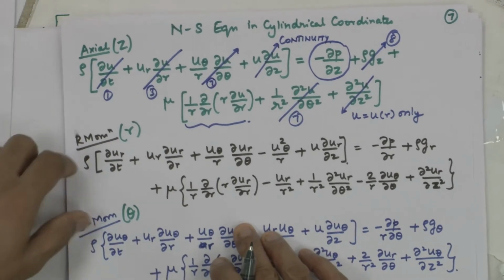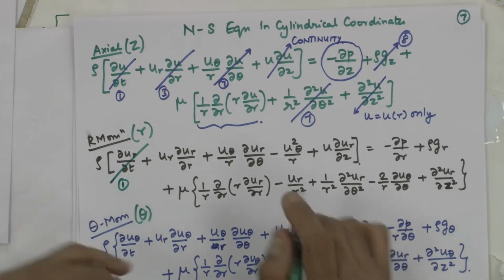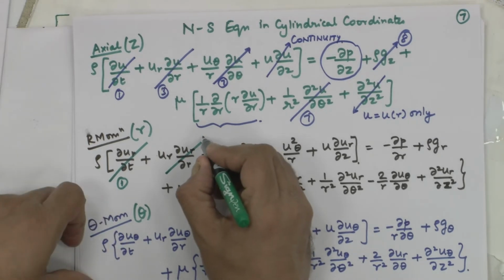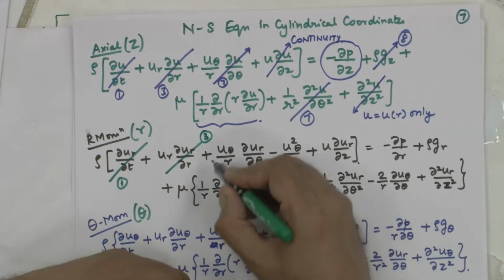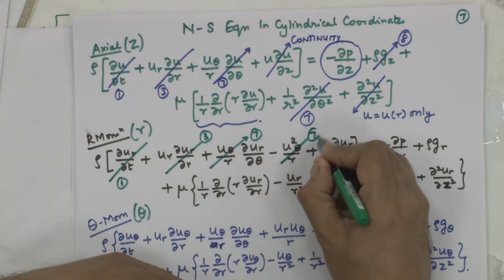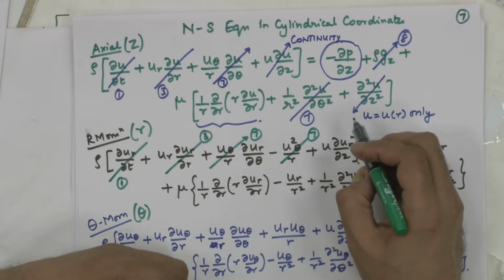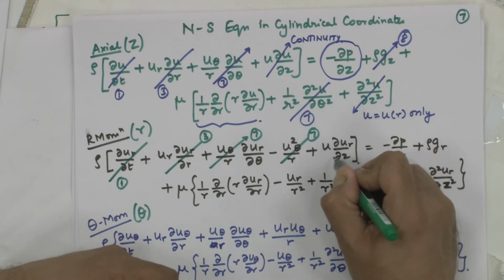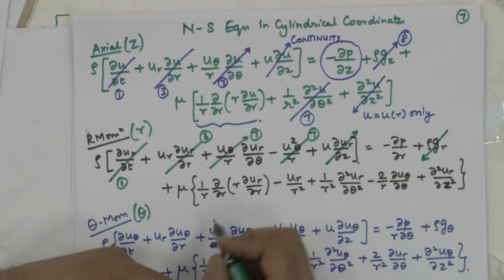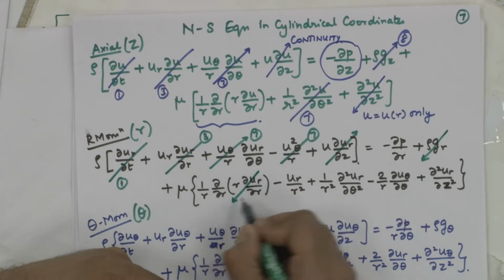R momentum equation, again you have steady state, this is assumption 1, u r is 0, no, it is a parallel flow problem. So, this is 0, u theta was 0, number 7. So, this also goes to 0, same reason for this. There is no radial component of the velocity. So, this also goes to 0, gravity is not there, this is all going to be 0.